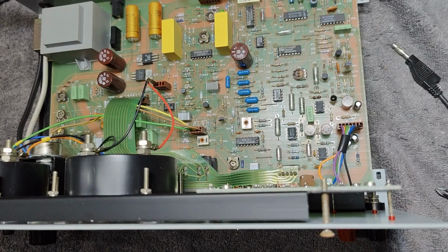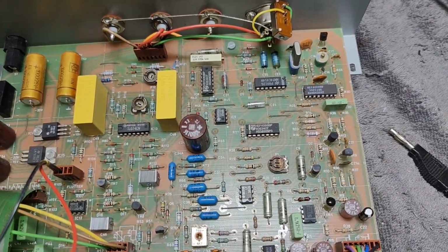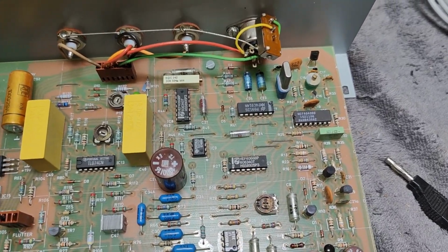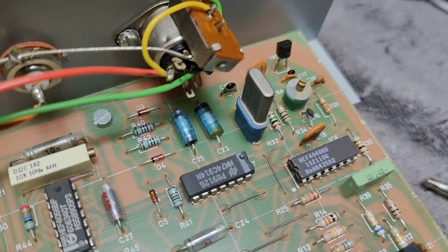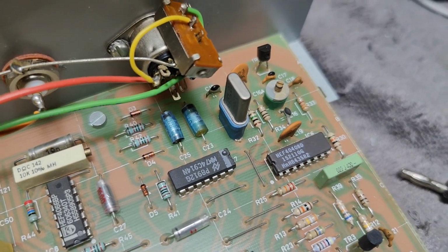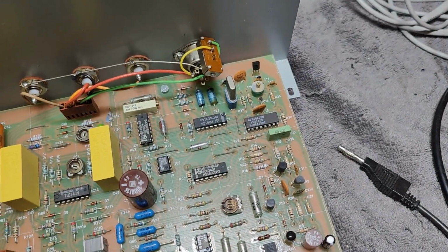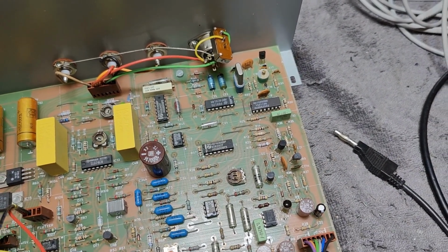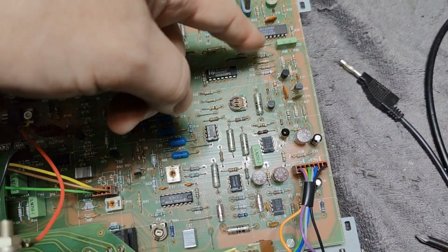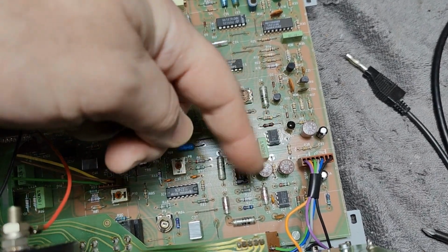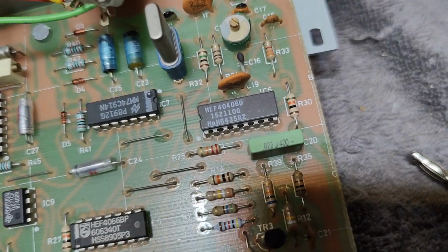Oh yeah, there's another really cool thing in this unit. Of course, this is all about making frequencies, but also comparing a frequency to some filters. And here is a crystal oscillator. And all this here is, of course, generating the exact frequency we need, the 3.15 kilohertz. So we've got some amplifiers and op amps and all that kind of stuff down here. And here is a counter,